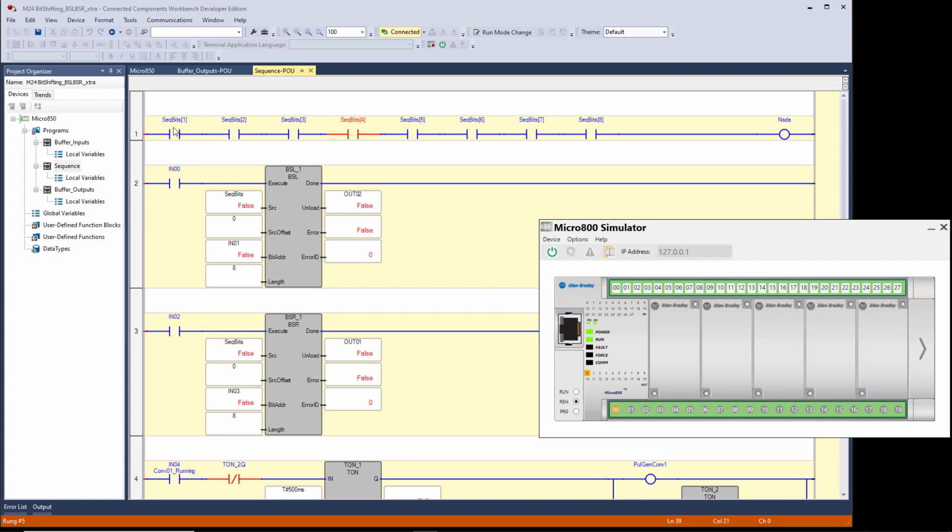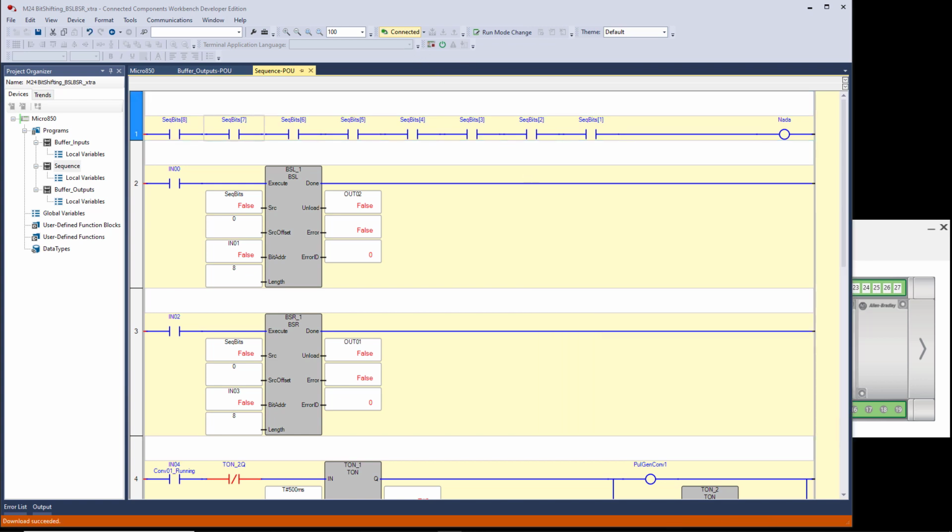So I'm going to pause and draw these differently, and then I'll be right back. Notice what I did. I flipped the sequence of these around, so the least significant bit is on the right side and the most significant on the left side. And if you're looking at a word in memory, the least significant bit is normally drawn on the right side. So if you shift left, that means you're shifting from a lower significance to a higher significance.